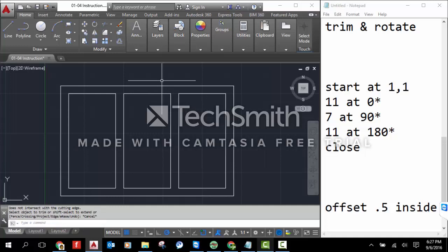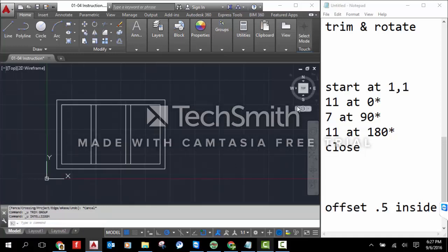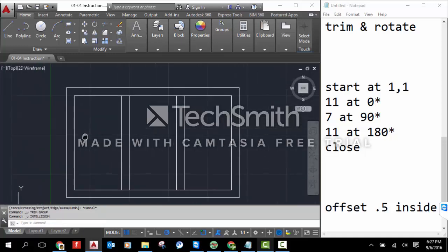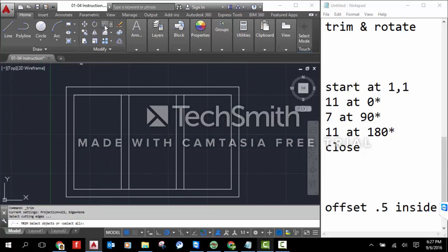So trim, again, what we did, and I'll undo so that we can see, is I clicked on trim. It tells me to designate boundaries, but I don't want to designate boundaries. I'm going to press enter so I can freely delete those little extra pieces. And so it takes the normal line and it separates it into small little chunks based off of the little boundaries that are automatically there. So I've used trim and I've set that up.